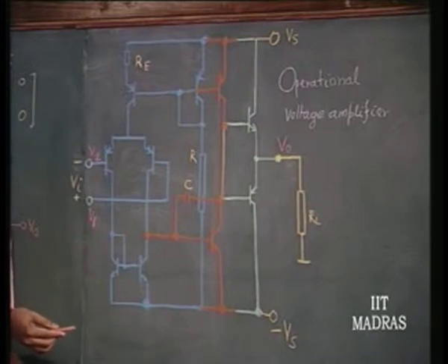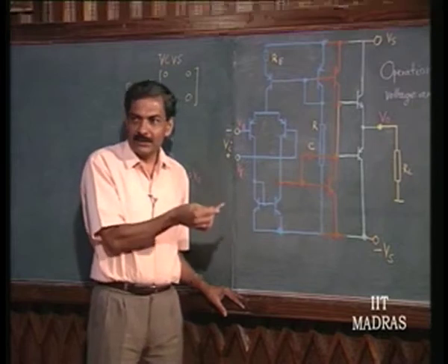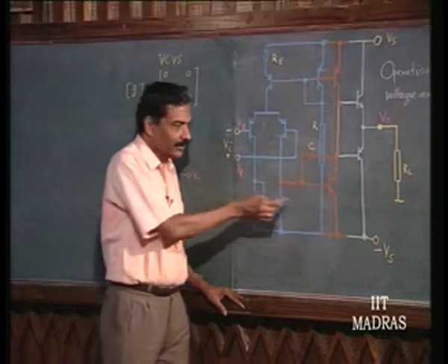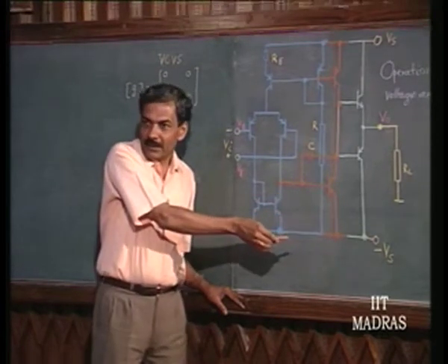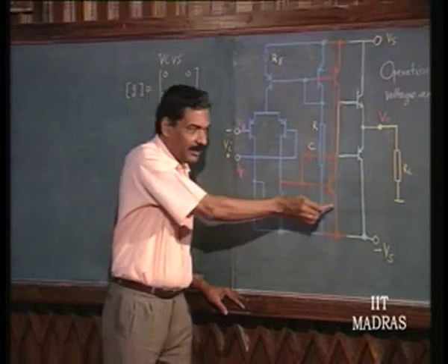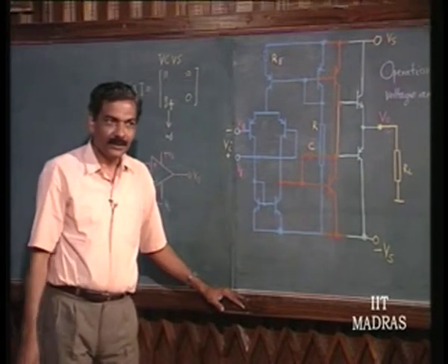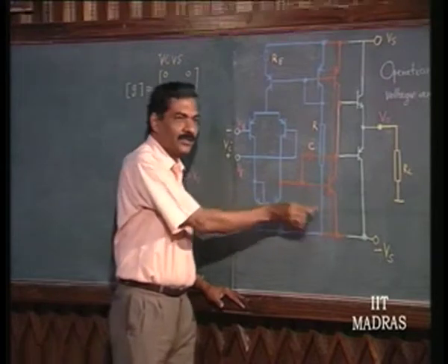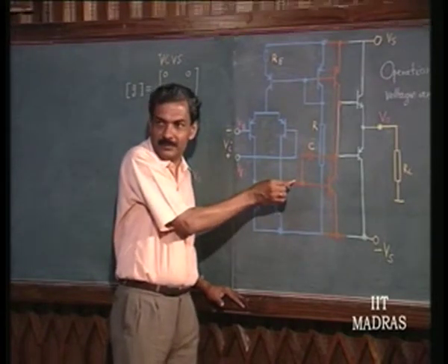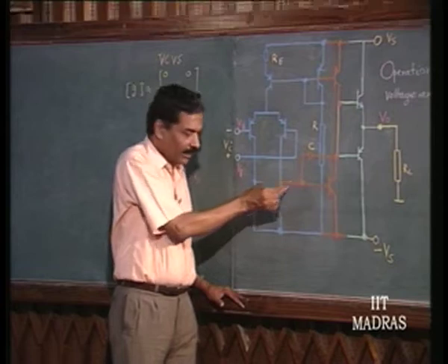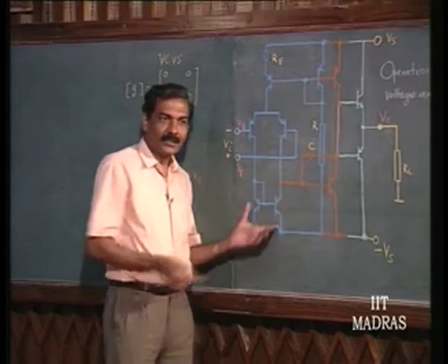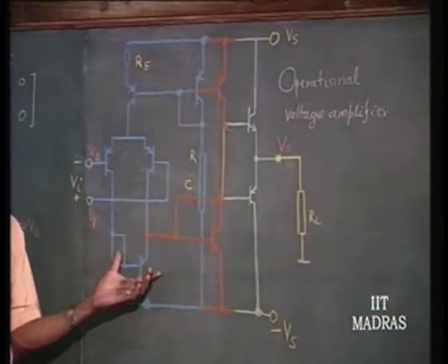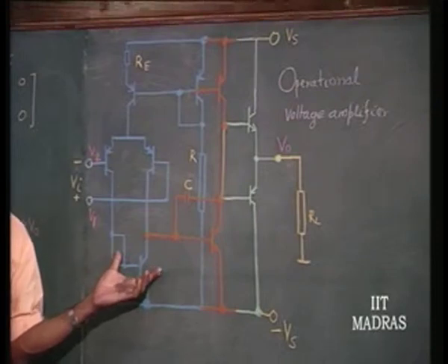Okay? And the next stage is going to be NPN, and it is going to have emitter connected to ground AC wise. That means emitter should be connected to minus Vs, and the potential here is going to be 1 diode above minus, okay? And therefore, we have naturally this acting as a suitable load without the need for any level shifting stage.